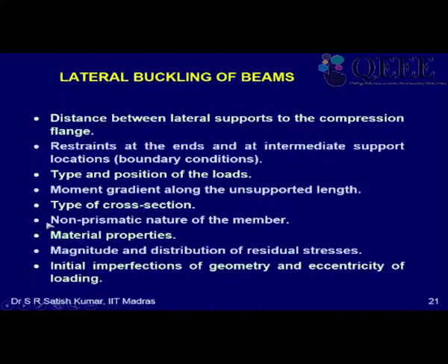Okay, but in beams even the shape of the cross section will matter, because warping etc. would depend on the shape of the cross section. Then of course beams can also have non-prismatic cross sections. We have seen yesterday that sometimes we may want to design tapered or stepped beams. Then of course material properties, distribution of residual stresses, imperfection in geometry, and eccentricity of loading.